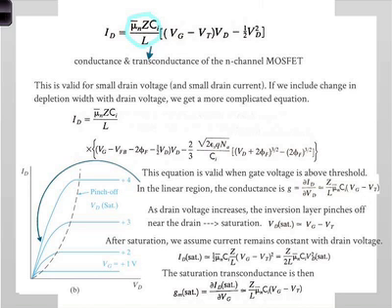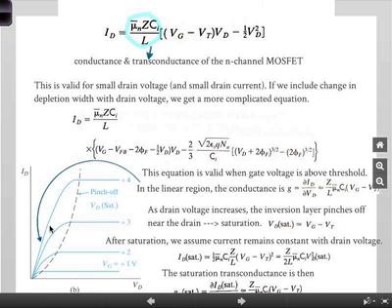What I'm trying to say is that you can use these transistors also for analog processing, which is getting more popular now because you can do low power processing and lots of very interesting things. We are talking primarily about digital processing here, integrated circuits and so on, but you can also apply these devices to do analog processing, because you get this transconductance gain, which can be controlled with the gate. So you have some interesting properties there. Anyway, you should be aware of that.